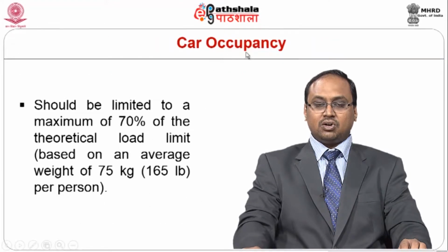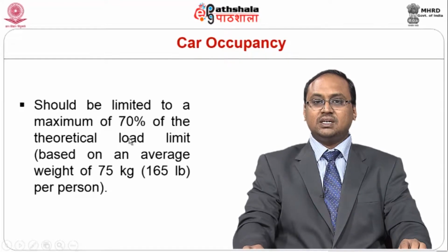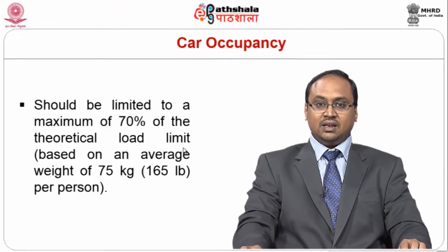Talking about car occupancy, it should be limited to a maximum of 70% of the theoretical load limit. Even though the numbers may say a certain maximum capacity, it is always preferred to keep the count lesser for the long life and the good workability of the elevator system.